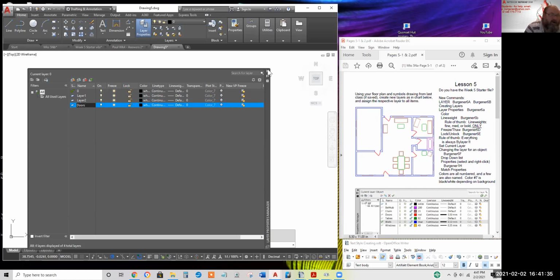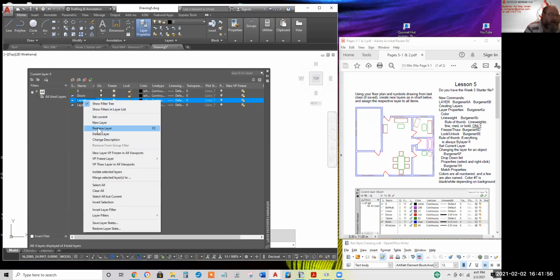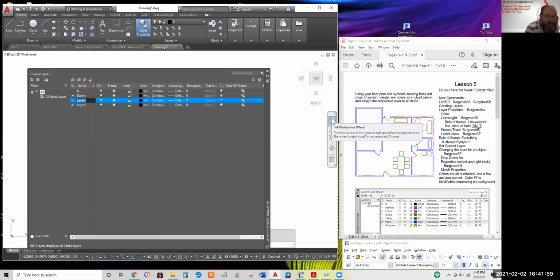Or you could close your layer property manager and open it again and come back and rename a layer later. There are a couple of different ways to rename a layer. Click on it twice with a slight pause between, or you can select it, right click and pick rename. Either way, give it a new name. I think your list below page 5-2 has a layer named chairs. So keep clicking new, name them now, or rename them later: Windows, etc.